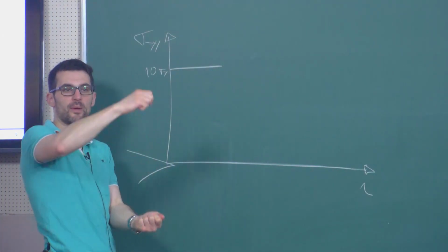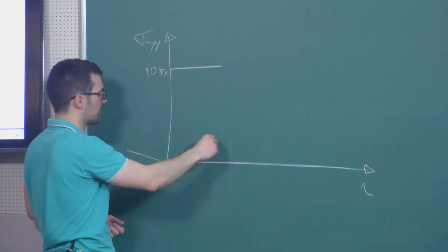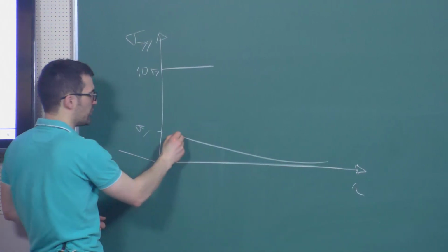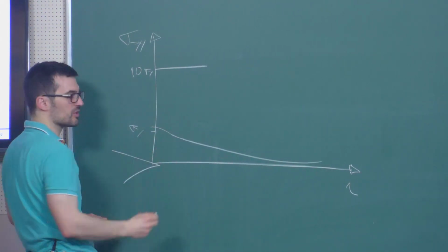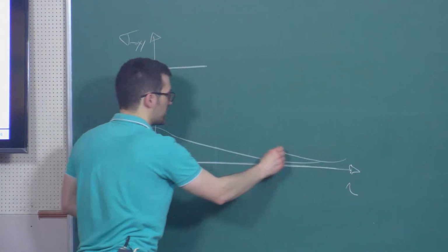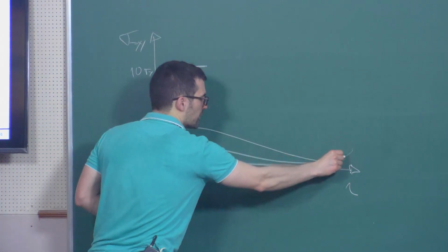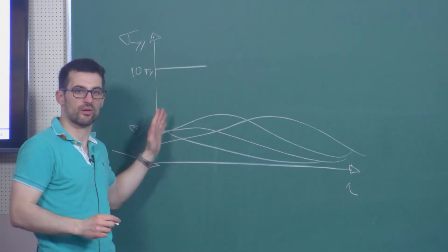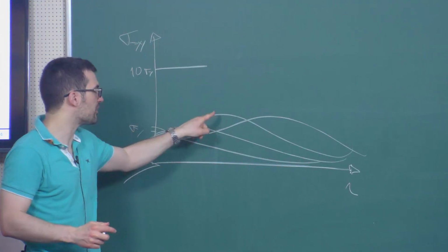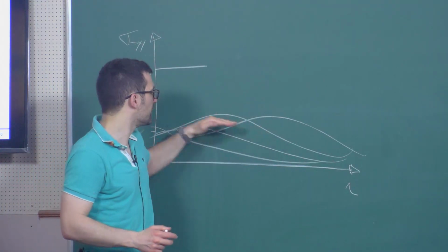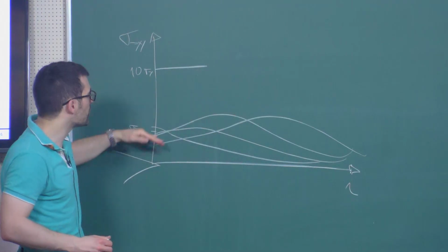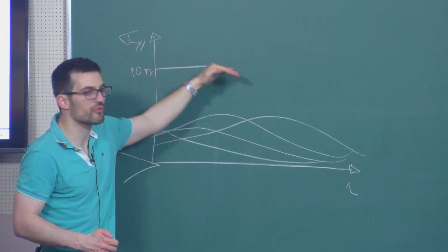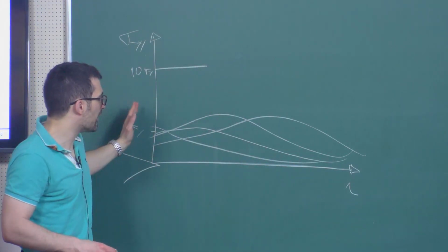So when you start loading a metal, initially your stress looks something like, I don't know, this is your yield stress. Your stress goes up, eventually you hit your yield stress, and then depending on your hardening, you do something like this. You keep increasing your stresses, and then according to conventional plasticity, you start doing things like this. So you never really get there. I don't know if you've seen that in fracture mechanics courses, but the peak of your maximum stresses moves away from the crack tip, but it stabilizes at a certain limit. So you never really get anywhere close to this. And not only do you need to hit this spot, you need to hit this spot over a sufficiently long distance. So that's why eventually other things happen.